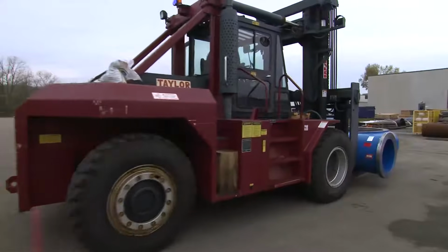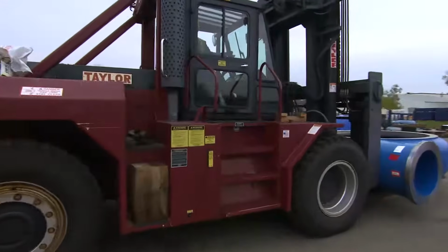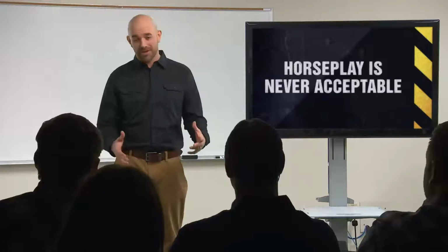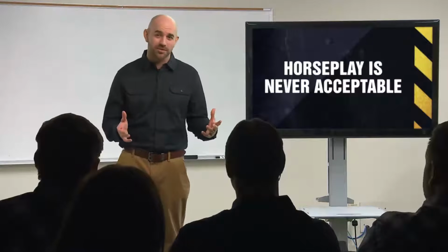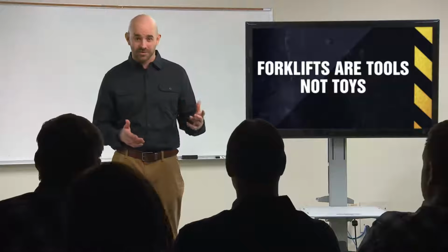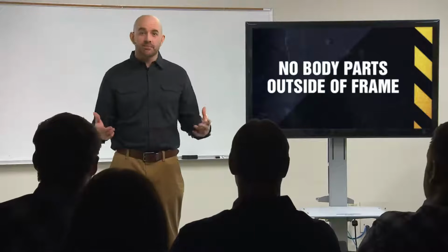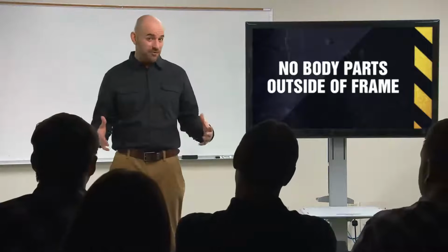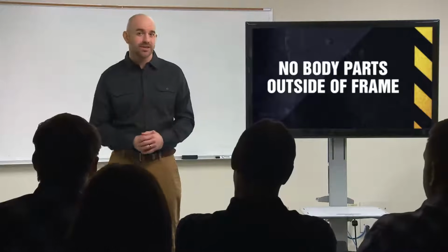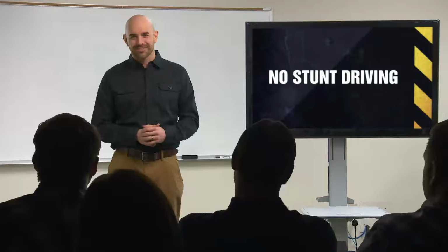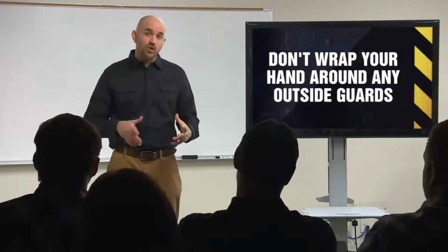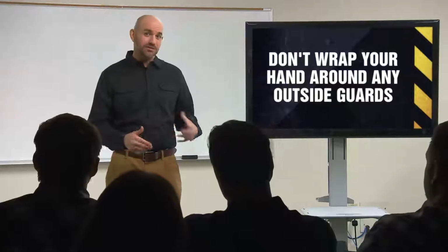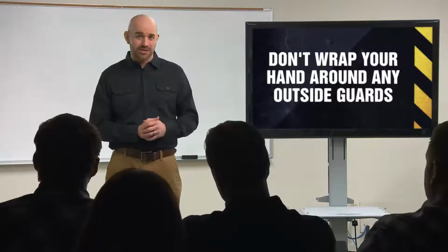Never exceed the speed limits of your work area and always go slowly enough to maneuver and stop safely at any time. Don't forget, horseplay is never acceptable. Forklifts are tools, not toys. Never travel with any part of your body outside of the forklift's protective frame. A hand or a foot could easily get pinched or crushed. And don't do any stunt driving. When driving in reverse, don't wrap your hand around any outside guards. If you do and the lift runs into something, your hand will be crushed.